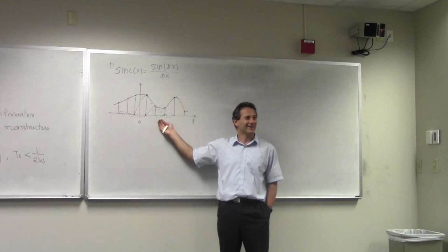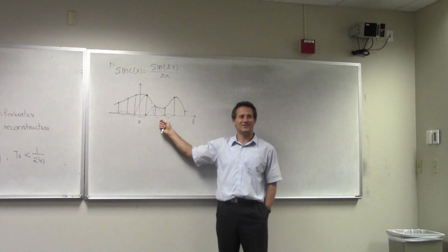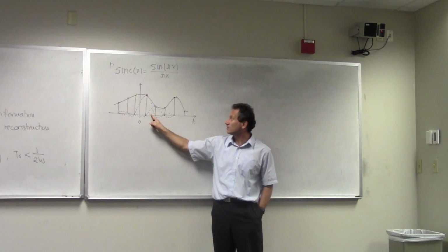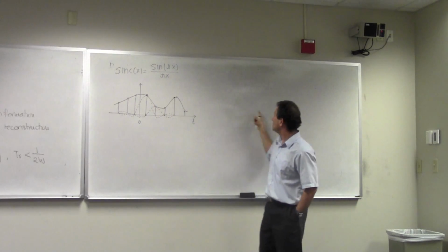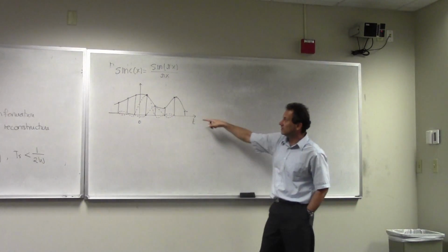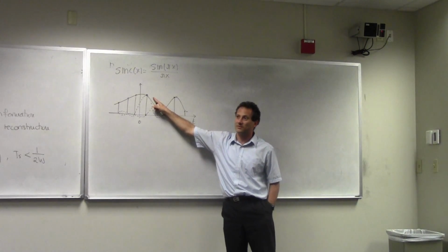So the sampling theorem says, yeah, you can do it without loss of information, but then not really, because you need to wait for an infinitely long time, and if I want to reconstruct what is happening here, I need a sinc that is way over here, whose tails are going to be contributing to this.